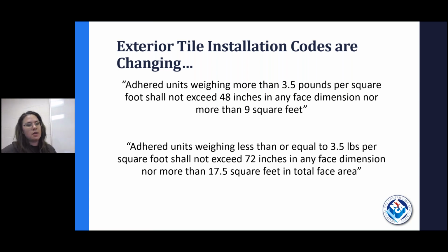They were very thick. Then, let's say maybe 7 or 8 years ago in the US, we started getting more and more of these gauged porcelain panels that were lighter weight. So they're starting to change some of the codes so that you can install these panels outside without mechanical fastening, provided they meet these two standards.